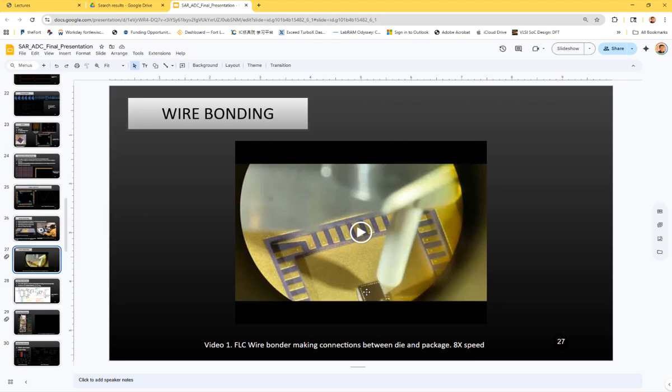So you can see this is a chip. So these are the little pads. These little tiny dots are the Metal 3 pads with the opening on the top. Okay, and you have Metal 2, Metal 1 down below that, and short to the circuits in the chip. And this is 1.5 by 1.5 millimeter under the microscope, and that's the package's bigger pads. And you are making connections from these little Metal 3 pads to these bigger pads, and eventually these are shorted to the pins of the packages, the 20 pins on each side.